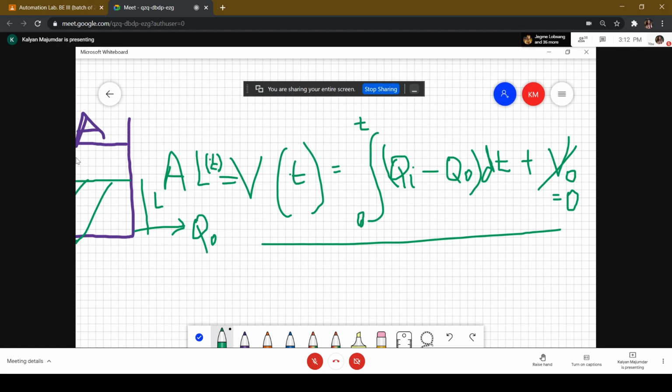Exactly using this approach, you can simulate the upper tank, and you can simulate the lower tank. I'm just restricting myself to the upper tank because for the lower tank we are not interested in the level, we're just interested in whether or not you have sufficient water. It's just one level switch there that you can use. But for the upper tank, the level is important because we are trying to ensure that the pump starts when the tank is empty, the pump stops when it is full, and so on. So basically, when you're trying to model the process, you've got to develop an equation, some kind of program which implements this particular equation, because that would be the implementation of the actual tank behavior.